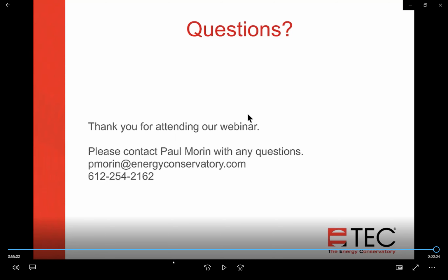Will the DG1000 offer reading in units other than pascals? It will read in inches of water column. It does have that units change. You have to go into the settings and change that. But that changes both sides of the gauge, so you can't read inches of water column and CFM, for example. When you switch it to inches of water column, you'll see inches of water column on both sides, and you'll just be in the pressure mode.